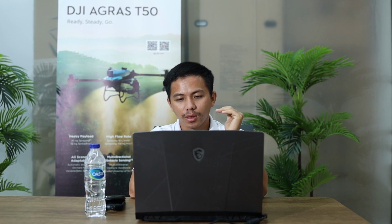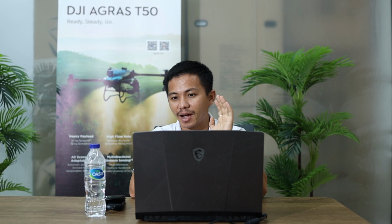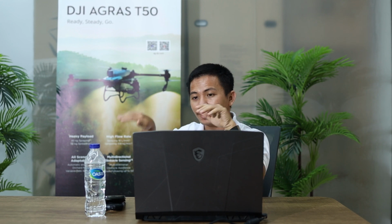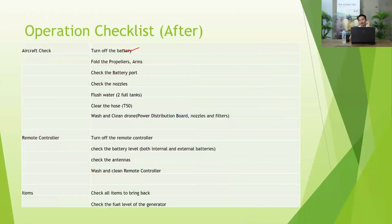Of course the manufacturer or any drone company will tell you, our drone can manage even if one propeller breaks, it stays flying. But I don't think the manufacturer will say just keep flying. Once one propeller breaks and you realize it, try to make a landing. If you don't land, yes, the drone is flying, but the balance is lost. So the other side or the ESC is running too hot, getting hot and bent. This is somehow related to before operation. Why? Because after every operation you need to do maintenance, cleaning, and checks.